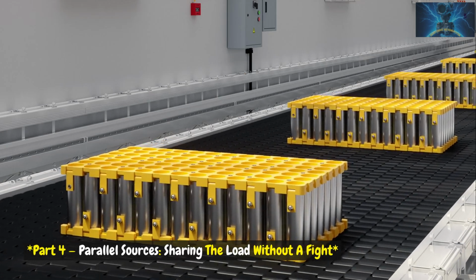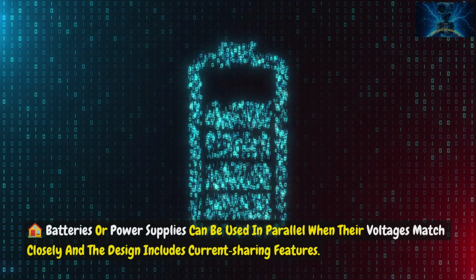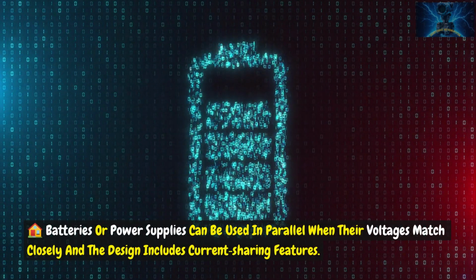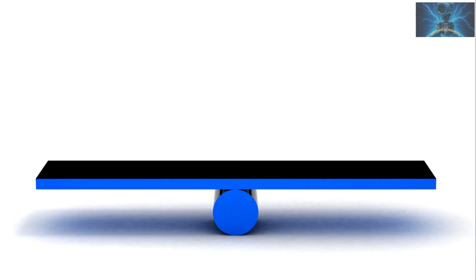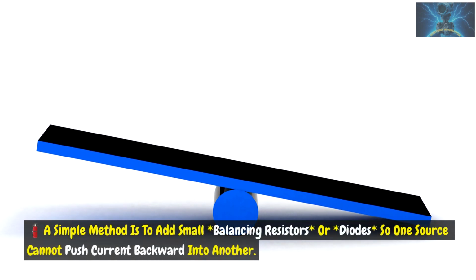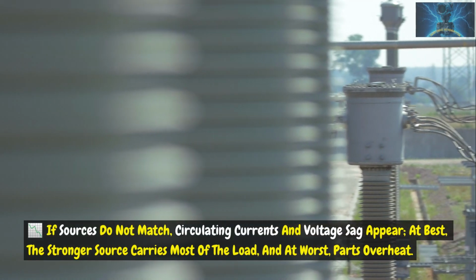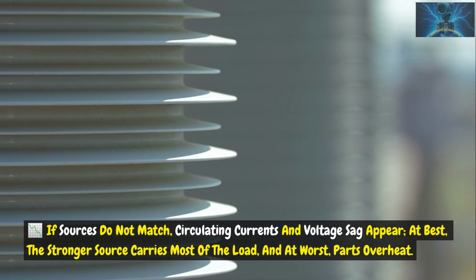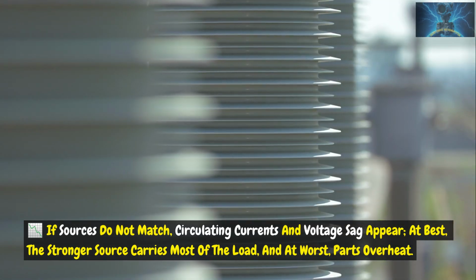Part 4. Parallel sources. Sharing the load without a fight. Batteries or power supplies can be used in parallel when their voltages match closely and the design includes current sharing features. A simple method is to add small balancing resistors or diodes so one source cannot push current backward into another. If sources do not match, circulating currents and voltage sag appear. At best, the stronger source carries most of the load, and at worst, parts overheat.